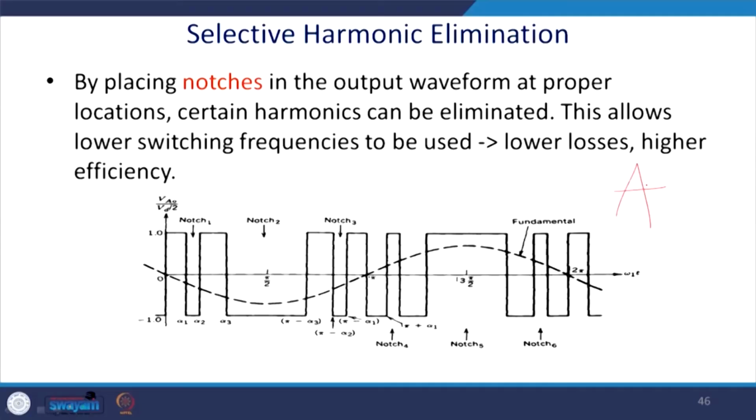Another issue is that with a higher power rating, we are required to reduce the switching frequency. For example, a GTO is operated below 1000 hertz, and this method is the preferred method mostly for GTOs or thyristors having commutations involved.